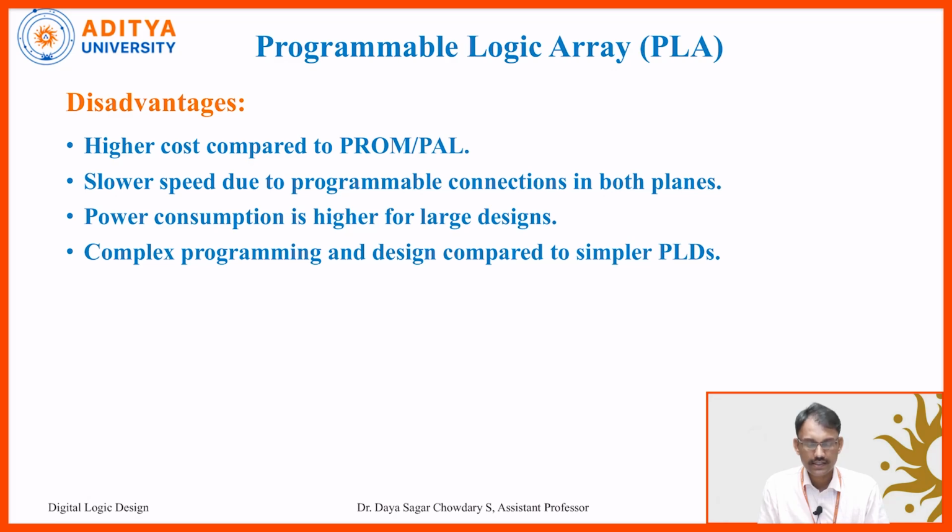Coming to the disadvantages, higher cost compared to PROM, PAL. So not only PLA, there are two more other terms, that is PROM, programmable read-only memory, and PAL, programmable array logic. When compared to these two, it has higher cost, because in PROM only OR gates are programmable but AND gates are fixed. In PAL, AND gates are programmable, OR gates are fixed, but in PLA both AND gates and OR gates are programmable. So that is why this is higher cost when compared to PROM and PAL.